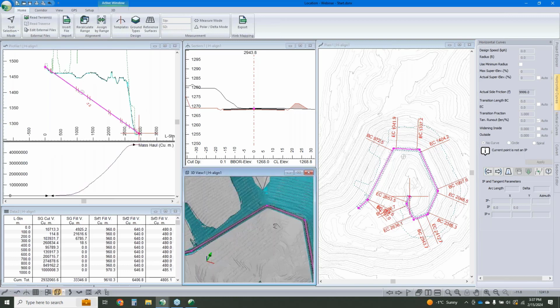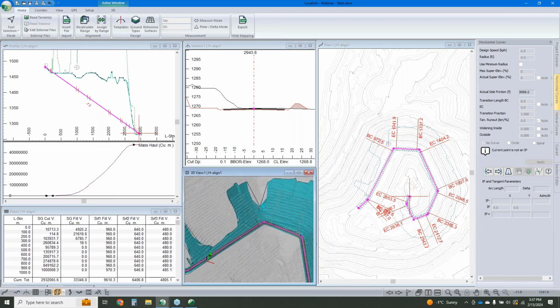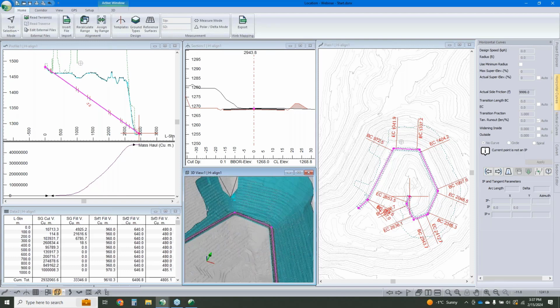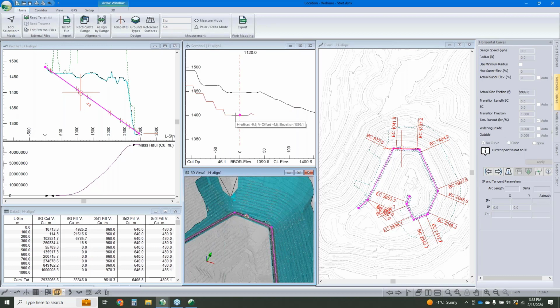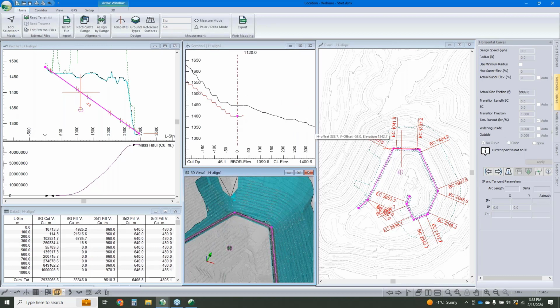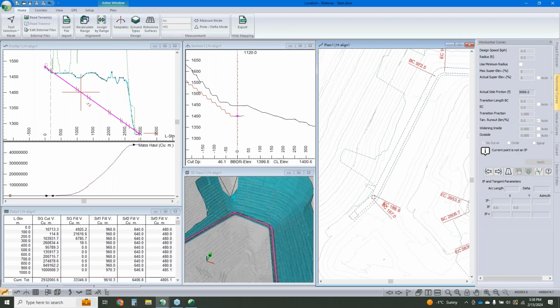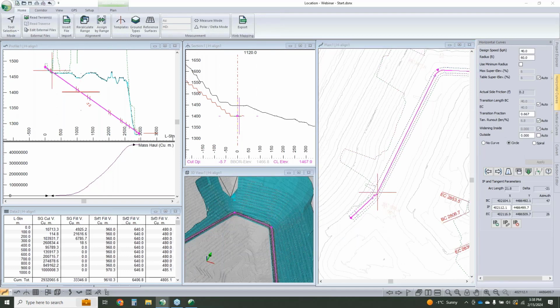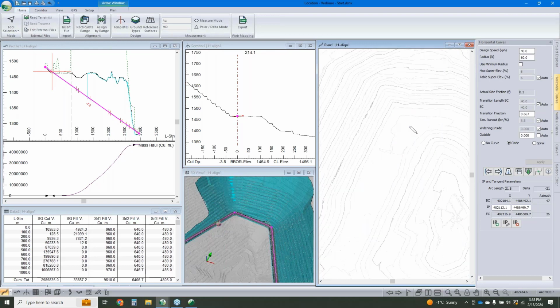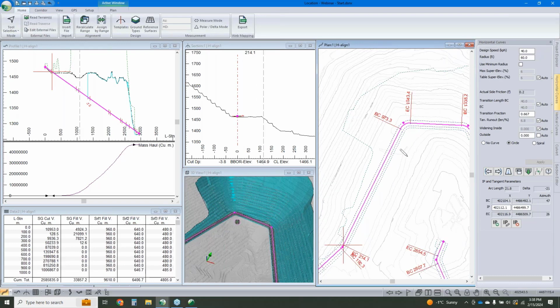But as I said, we want to avoid stuff like that, where we're taking down way more than we'd like. So here's just the software being an easy to use dynamic tool. Well, we can move this around and we can make sure that we don't have our cut slopes screaming up the pit any higher than we'd like. So this is, to go back to that question that was asked, this is where we're not necessarily optimizing the ramp to minimize our cuts and fills, because we plan to take all of this. It's just all this other stuff that we'd like to avoid.